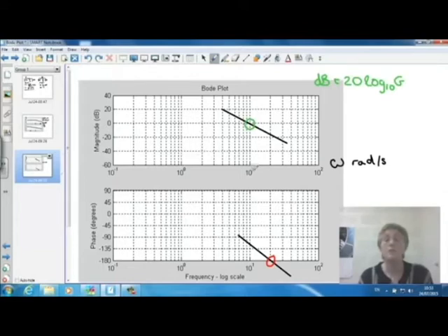So what we want to do is check that we have enough gain margin and phase margin that even with changes to the gain due to the environment, for instance if the temperature increases, we're not going to reach the point where the gain is still positive when the phase change at the output is 180 degrees.